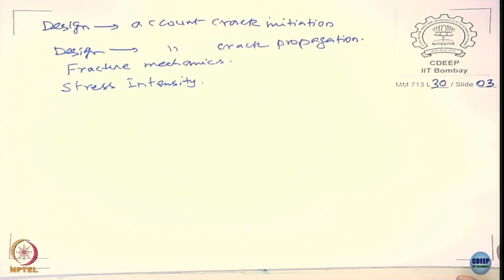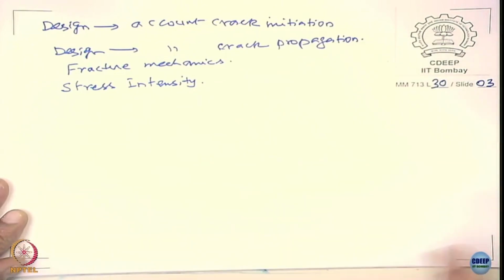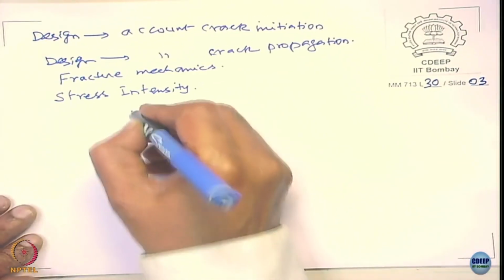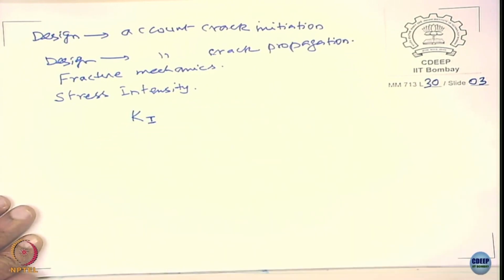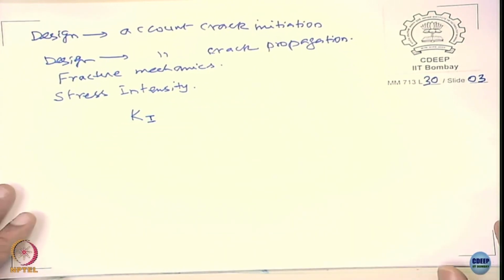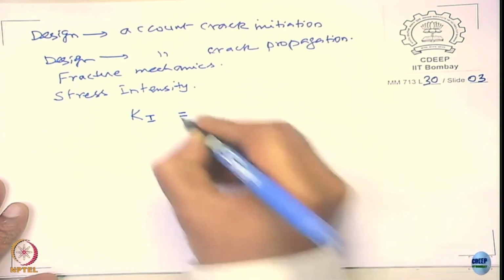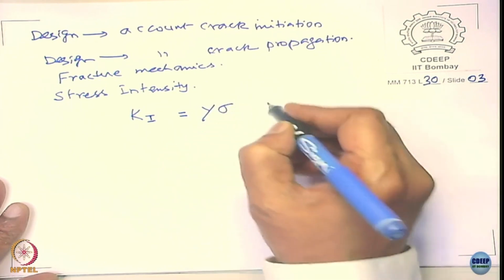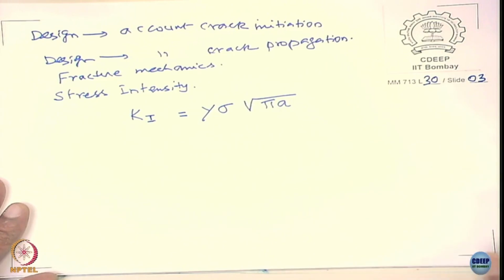Okay, what is stress intensity? And you of course have different modes of loading. For mode 1 of loading, K1 is given by Y sigma square root of pi a, right?